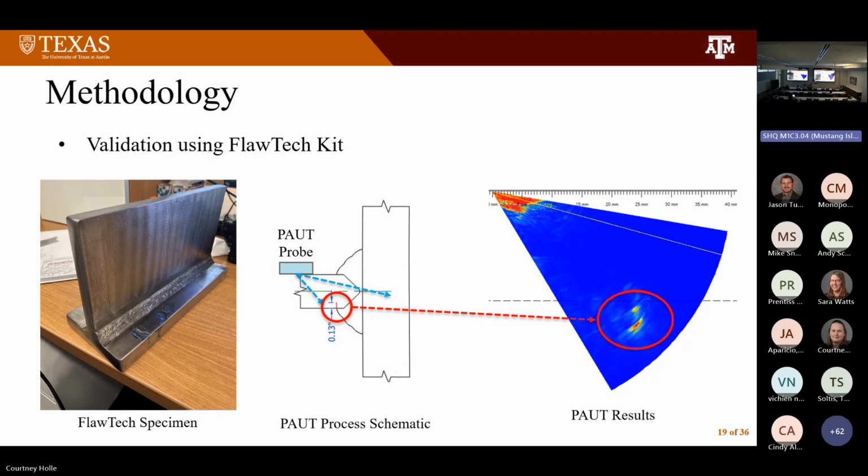What's nice about our laboratory tests is that we can get in and really characterize what's actually there. And I remember we were working with VJ at the time, and they were doing some things on some high mass poles where we knew there were cracks because he had already found them, and he went out and looked again and said, I can't find them. And you find out, well, the sun was shining on a certain side of the pole and it made it bend a certain way, and the crack suddenly closes, and then it's harder to find. So we want to produce some specimens that somebody can use to go in and say, I should be able to find these cracks.